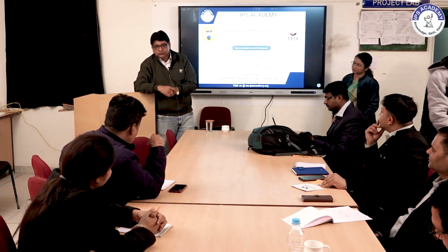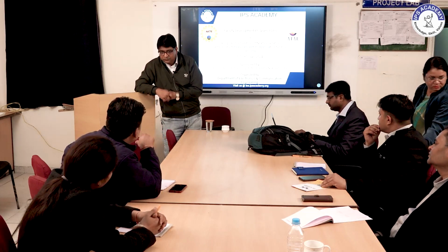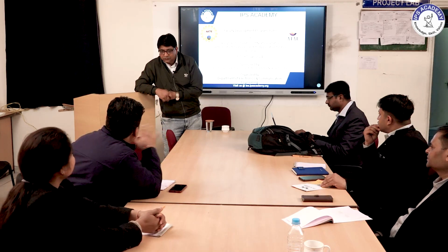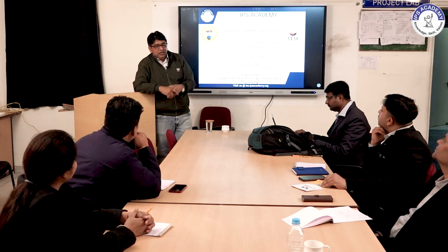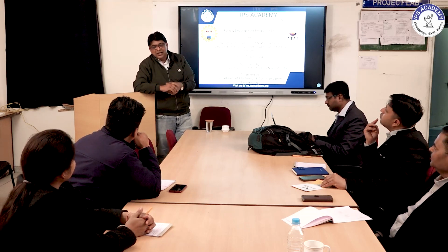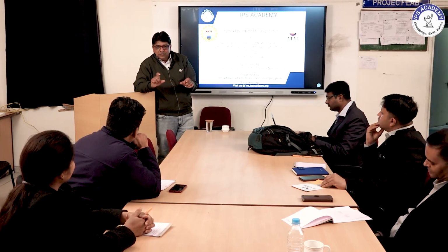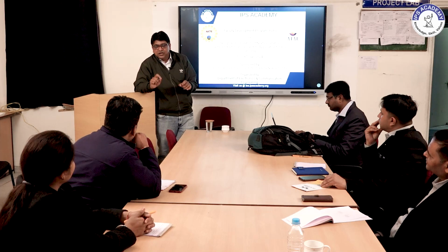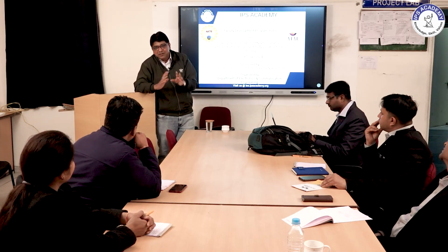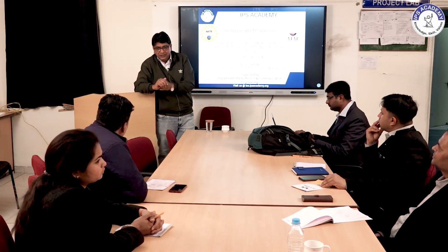Sir, in your definition, you are telling that in a short channel, the gate length will be comparable to the depletion layer. So how much comparable? That means 50%, 70%? No, comparable means if it is going to be equal. Suppose the channel length is 45 nanometer, and the depletion width at the drain side is around 35 nanometer like that, so it is comparable. Yes, like that we can do it.